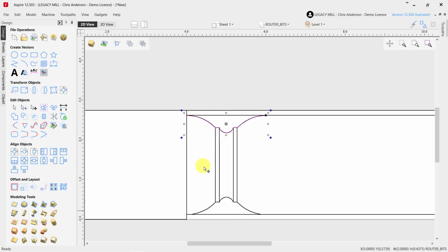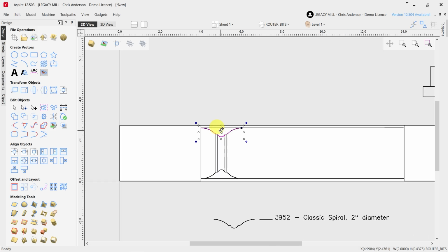So the stock is continually rotating during that plunging motion, and once it gets to the actual depth, it's going to finish rotating a full rotation around the circumference, and then the cutter is going to lift straight up and it is done. Okay, it's a very simple but fast process that takes place by having the cutter positioned at a single point in the x-axis and then plunging while rotating continually. All right, and we can repeat that as many times as we wish.